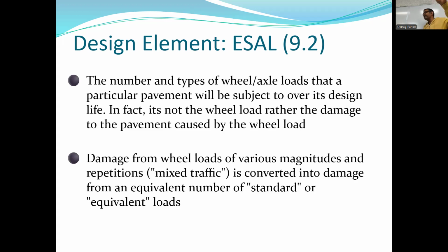Even though we approximated that with a linear function in our module 1, I do want to emphasize that this is kind of similar. In this case, it's the fourth power formula. So if you have a low ESAL load for a pavement, it doesn't cause much damage. But as the load increases, the damage to the pavement increases using a fourth power formula.